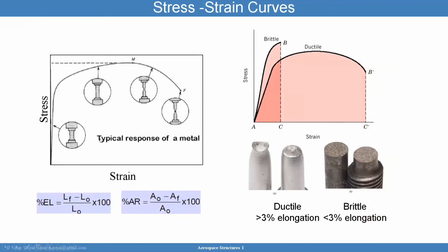Here, what you can see is the response of the metal as it's been loaded. And you can see that as I increase the stress, you will start seeing some necking if it's a highly ductile material. And when it reaches this point, that necking becomes so severe and the cross section so deformed that the structure fails. And we look at that, and that's the area reduction. The greater the area reduction you have, the more ductility we're talking about. And more importantly, the elongation and the area reduction will go hand in hand. So the higher the elongation, the higher the area reduction typically.